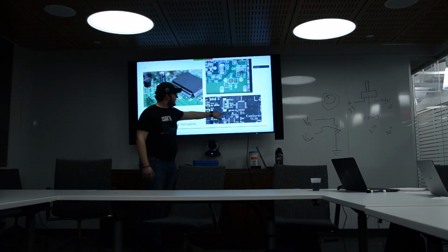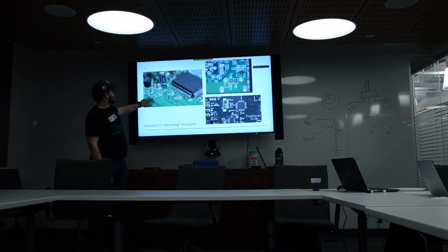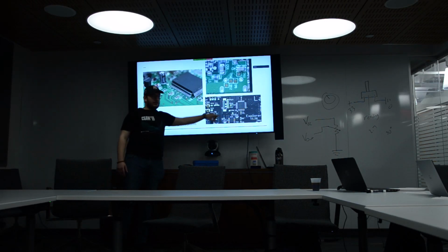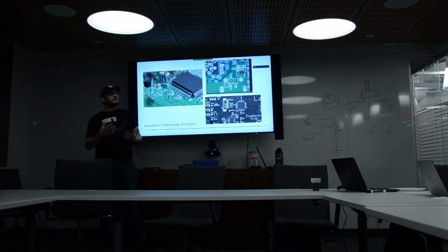And then right over here, and on this one also, this one's probably actually JTAG. You can see that they definitely meant to put a header here. They definitely meant to put some kind of port here, but they didn't. So it was probably used when they were developing it, which means that it's probably still connected to some goodies if you can connect to it and see what's going on.